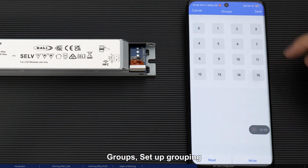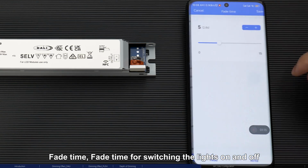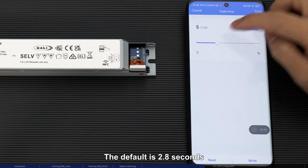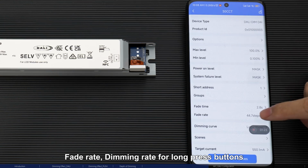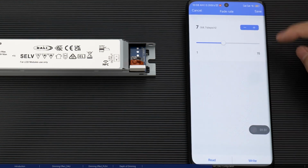Groups, set up grouping, which can be divided into multiple groups. Fade time for switching the lights on and off, and also for scene switching. The default is 2.8 seconds. Fade rate, dimming rate for long press buttons. The default value is 7.